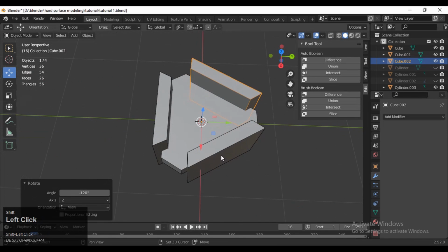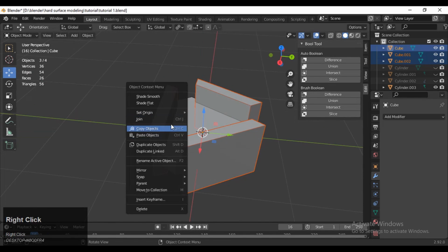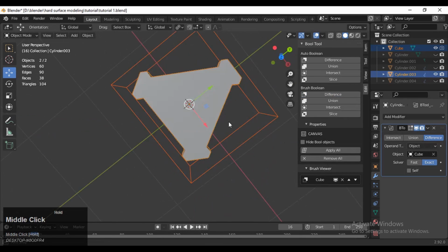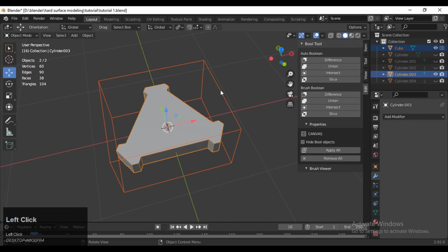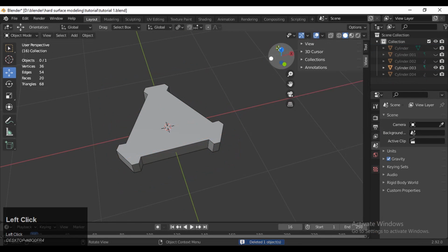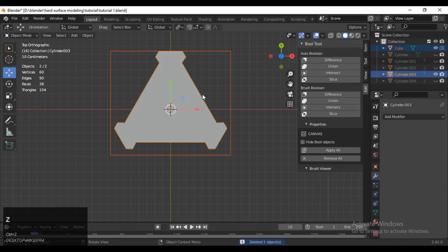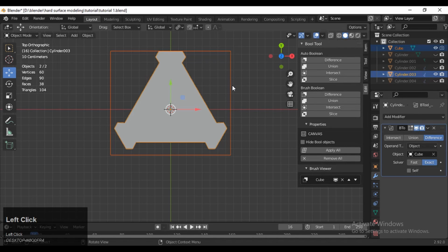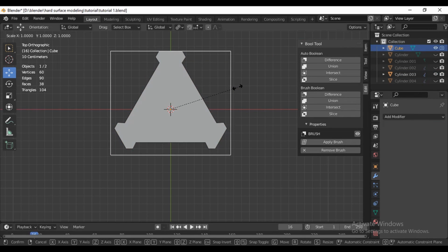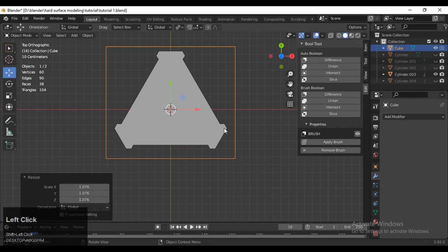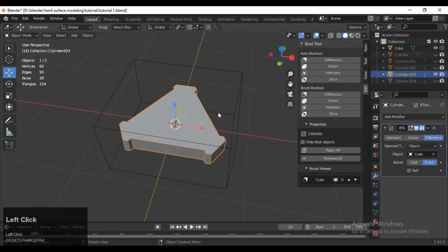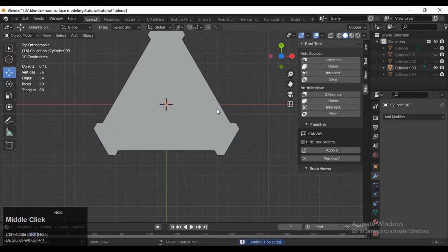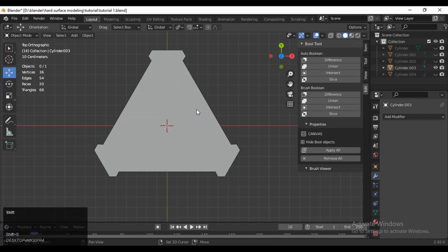Then select these 3 cubes and join them together, and then you need to use the Bool Tool, which is a free add-on, and then enable that Bool Tool modifier which will be created in the modifier tab. Before that, if you want to adjust the scale, then adjust the scale and then apply that modifier. It just means the boolean modifier, it creates a boolean modifier, and Bool Tool is a free add-on, so use that, and it is installed already in Blender.